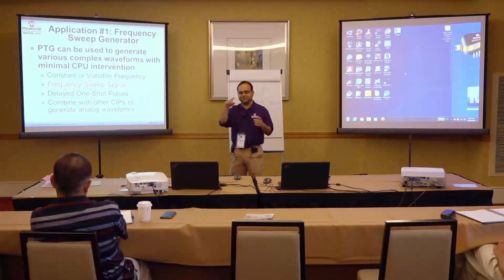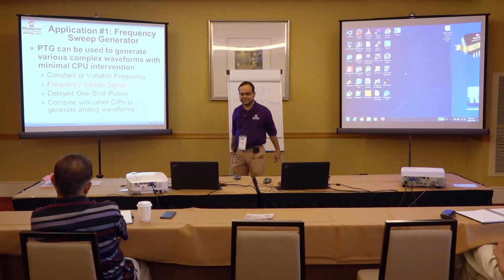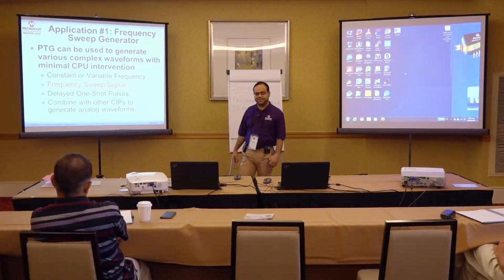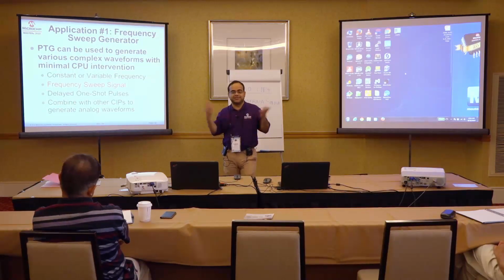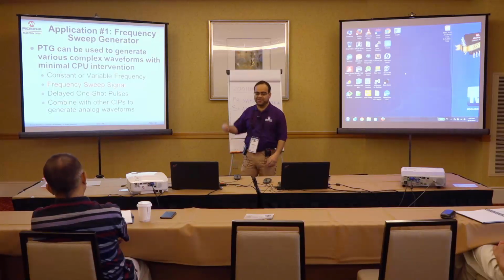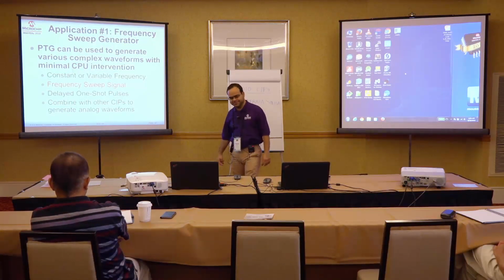You could generate a one-shot pulse, or you could also trigger off an incoming pulse, use a specific delay, and generate an output pulse. So there are a lot of different things that are possible. Or you can combine it with other core independent peripherals and even generate some analog waveforms, maybe with the op-amp and comparator and so on.